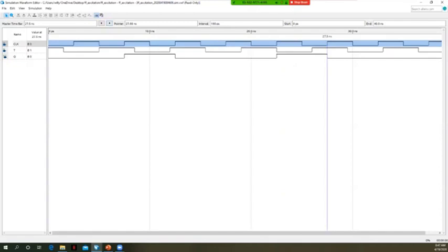Let's go here where we have this rising edge. T is definitely a 1. Q was a 1. It toggles back to 0. Next rising edge, T is a 0. We hold state. So Q is a 0. It retains its state. Next rising clock edge, same thing. T is a 0. We hold state. So you can play with these waveforms a bit to get this to toggle more consistently if you want, or to see it holding state when Q is a 1.